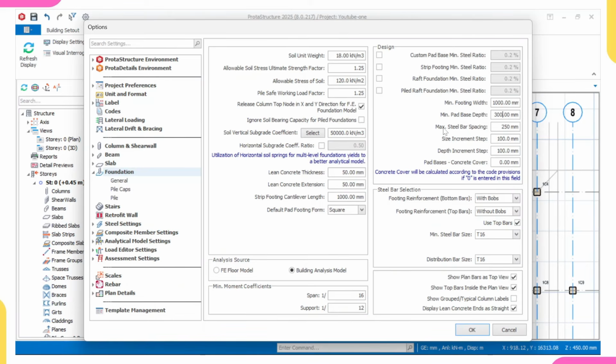Then coming over to maximum steel bar spacing, I'll leave it at 250. But remember what I told you, that even in footing, because of quality, I always like to go with a spacing of 200. So for that, I'll just do 200 because I know that 250 will pass.